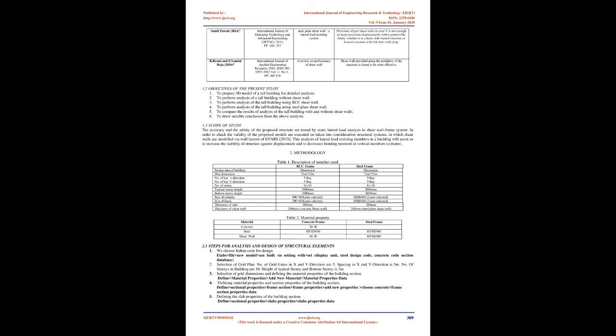Sumit Pawar, 2014, 4. International Journal of Emerging Technology and Advanced Engineering, IJETAE, 2014. Pages 244-252. Steel plate shear wall, a lateral load resisting system? Provision of part shear walls in Zone V is not enough to keep maximum displacements within permissible limits, whether it is a beam slab framed structure or framed structure with flat slabs with drop.